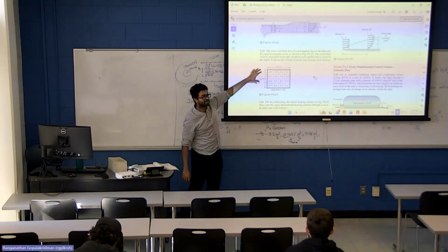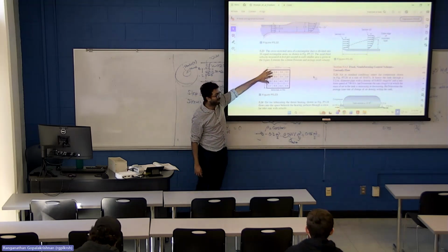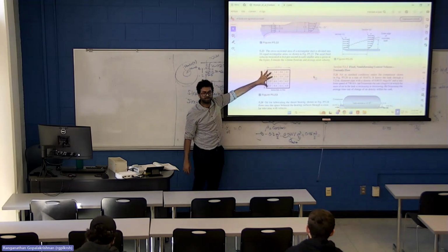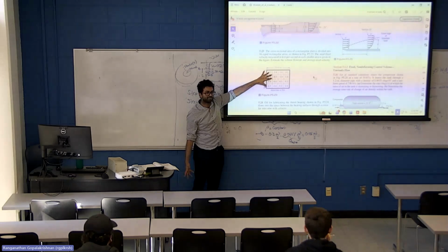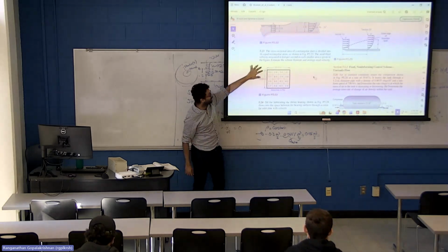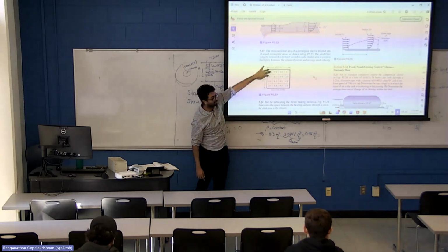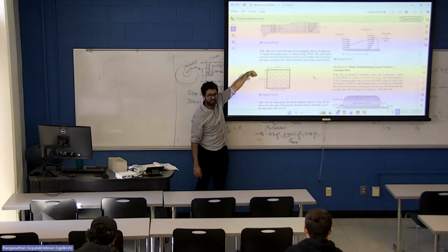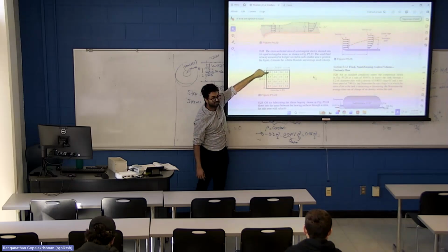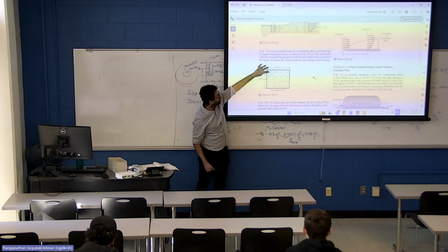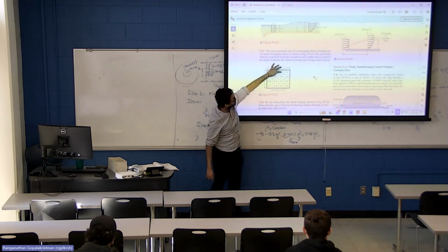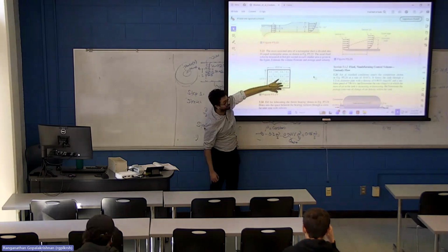So if you have a large duct, in practice, nobody will measure the flow rate of a large duct with any flow meter. What they would do is discretize this cross section into segments, like 16 segments here, have a velocity probe, stick the probe at the center of each segment, and read out the velocity in each segment, like here, 16 values.